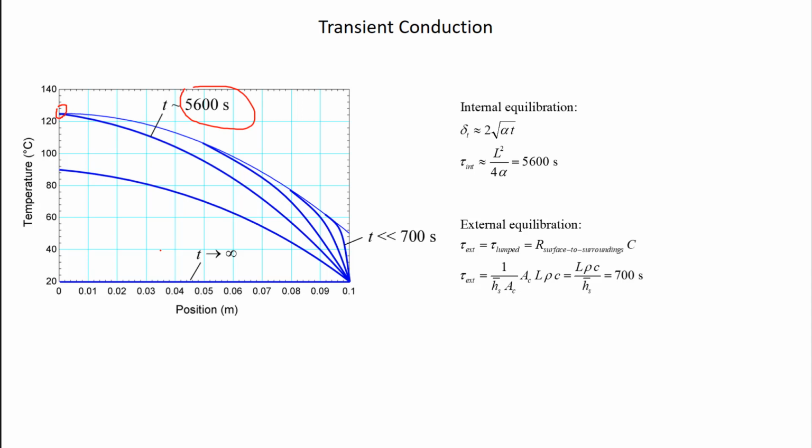But there are times where what's going on is very interesting and you need to solve it more exactly, right? These are not exact solutions. And if that's the case, you'd move on to some of the analytical techniques and numerical techniques that we're going to talk about next. But even so, in your back pocket, you want to have these time constants. So when you get answers, you can compare them with your physical understanding of what should be happening in this conduction process.